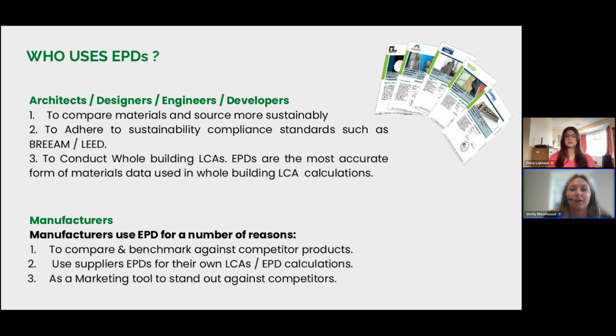They're also used in the later stages, so actually in procurement and when you're specifying particular products. So maybe you've decided that you want to use wood fiber insulation, and now it's down to getting to the nitty gritty of which wood fiber insulation manufacturer has the greenest product. So actually comparing manufacturers side by side as well. They're also used to adhere to sustainability compliance standards such as BREEAM or LEED.